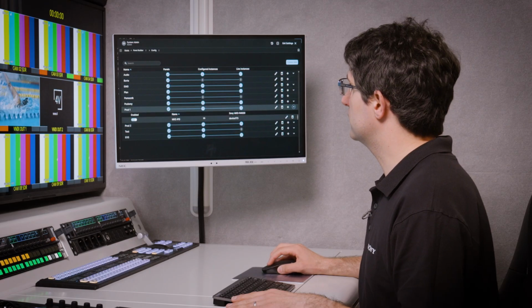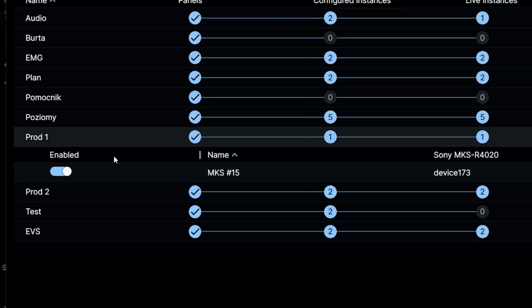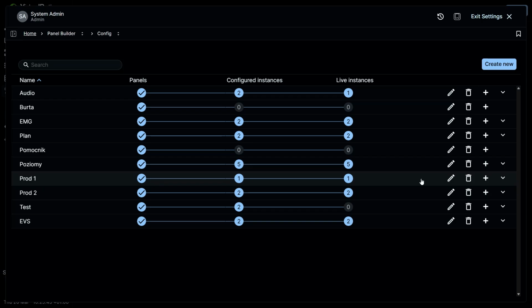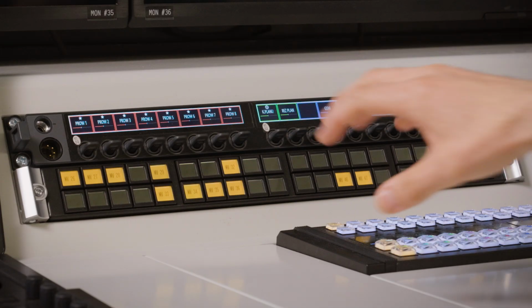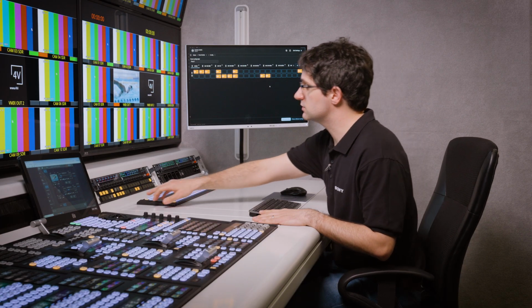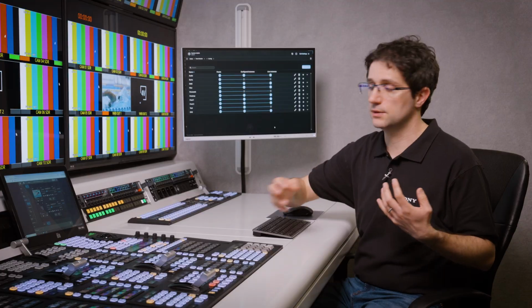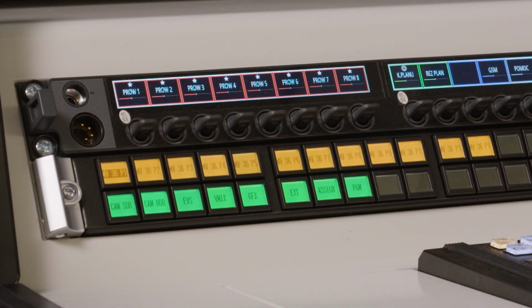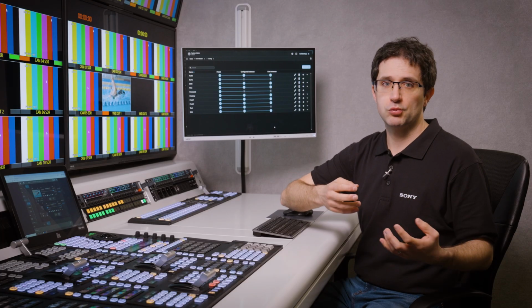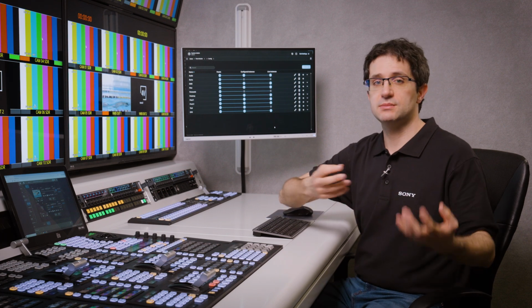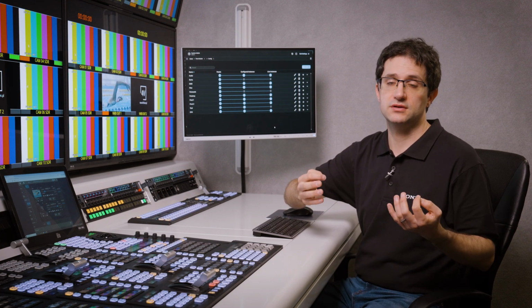Once you've added your configuration into the application, you can enable it or disable it by toggling this button. To edit the core panel itself, you press the pencil icon, and this brings up the interface related to the home screen, as you can see here. In front of me is Multiviewer 36, so I'll press this button, and this displays a range of different bits of information. On the top here, you have our destinations that relate in this instance to our multiviewer. Then underneath, in green, we have our source groupings. These enable operators to group like sources to simplify making those crosspoints when you need them.